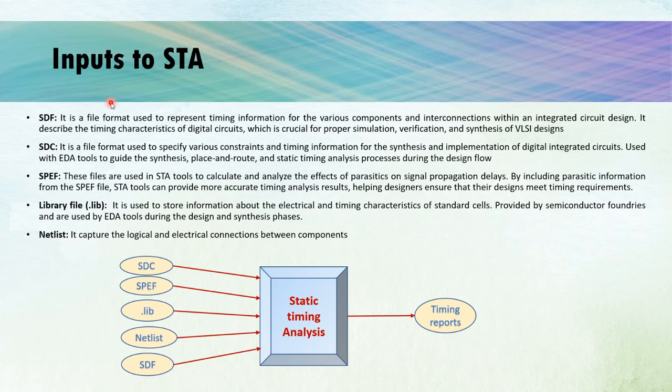So now we will see the inputs to static timing analysis. The first input to static timing analysis is the SDF file. An SDF file is a file format used to represent the timing information of various components and interconnections within the integrated circuit design. It's a standardized format that helps in describing the timing characteristics of the digital circuit. And this timing characteristic is very crucial for the proper simulation, verification, and especially synthesis of the VLSI design.